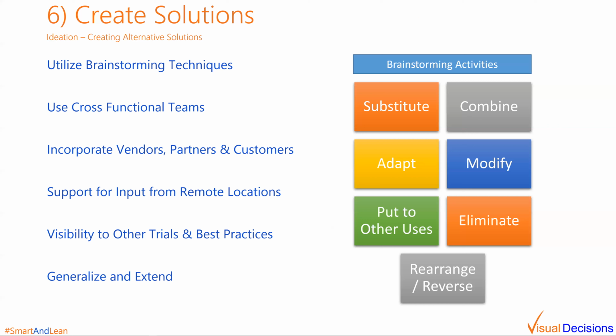So we gathered the process engineer, the operator, the supervisor, and the maintenance team at the line to brainstorm different solutions. And in the end, we put in two key fixes. The first was to fix the alignment of a joint in the feed that was causing the bottles to jam in the first place. And the other was an andon light to let the operator know right away when the filler, which was the gating process for the line, stopped for any reason. And that improved the OEE and the overall performance of that line dramatically.